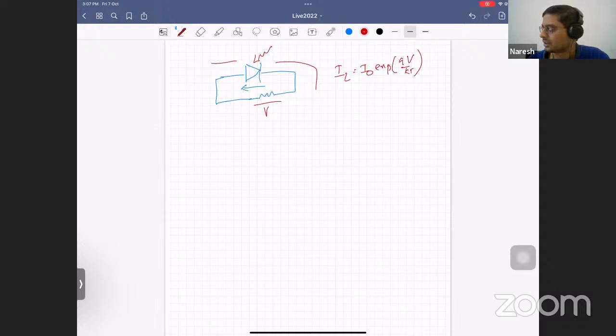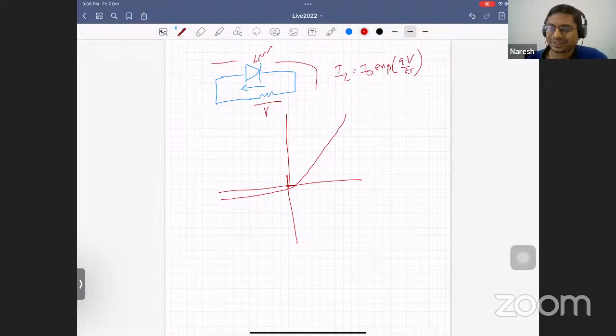All right. So you see that's why the quadrant also, it's not in the first quadrant. If you have a regular diode, this is how your IV characteristic is. This is your regular diode. But for the solar cell, we actually flip it. Just go and take a look at it, okay? It's actually current generating. It's not in the first quadrant. Take a look at where it falls and all that. It will become clearer, otherwise we'll talk separately.